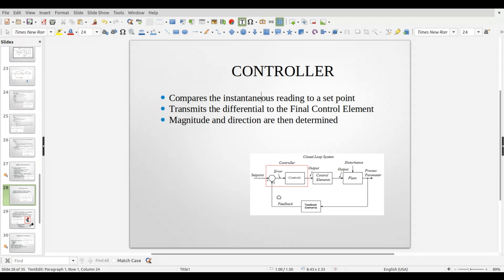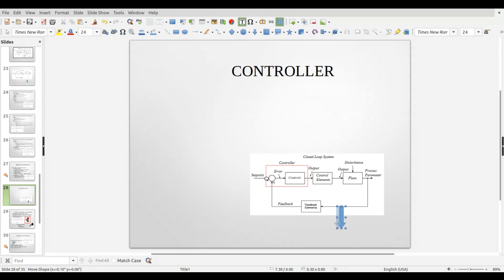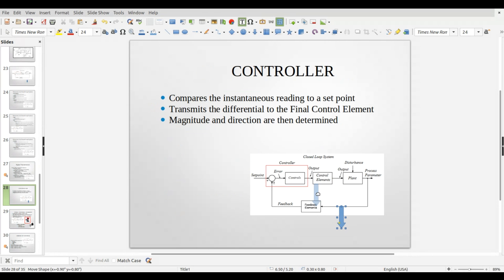At the time that we read the inputs, the set point is compared to the feedback value from our sensor instantaneously, which means when that scan is at that point, we're reading that value right now. Okay, but there will be a delay before we generate our output.